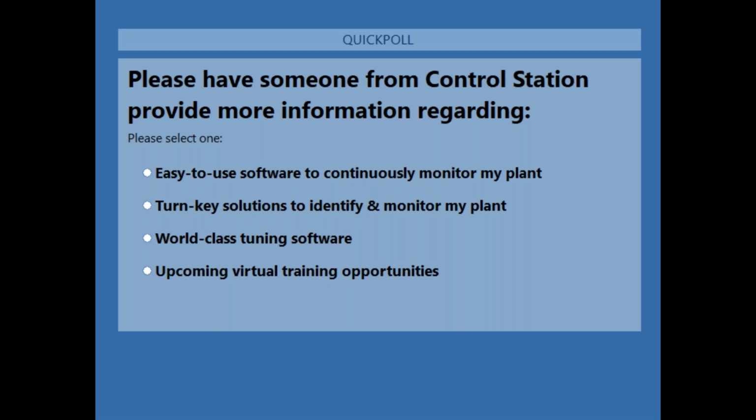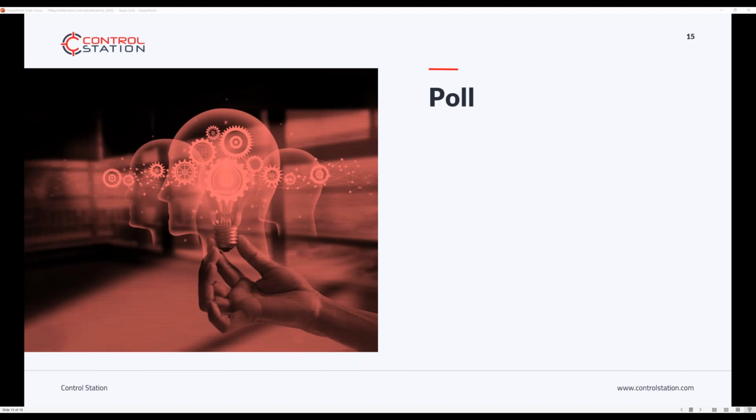But the future of SCADA is different levels, right? You've got the information that is needed to run the plant, but now you can start to pull in data into your SCADA on the performance and behavior of your system, right? Not just, hey, am I producing product? It's how well am I producing product? And SCADA systems now are starting to be much more intelligent with being able to bring in data from other sources, right? They're not just designed to look at the control layer and bring up the data. They're starting to interface with lots of different data sources, right? So they can consume data from REST or from other third-party tools, put up there, hey, look, there's performance issues with this. So SCADA can start giving you performance issues.